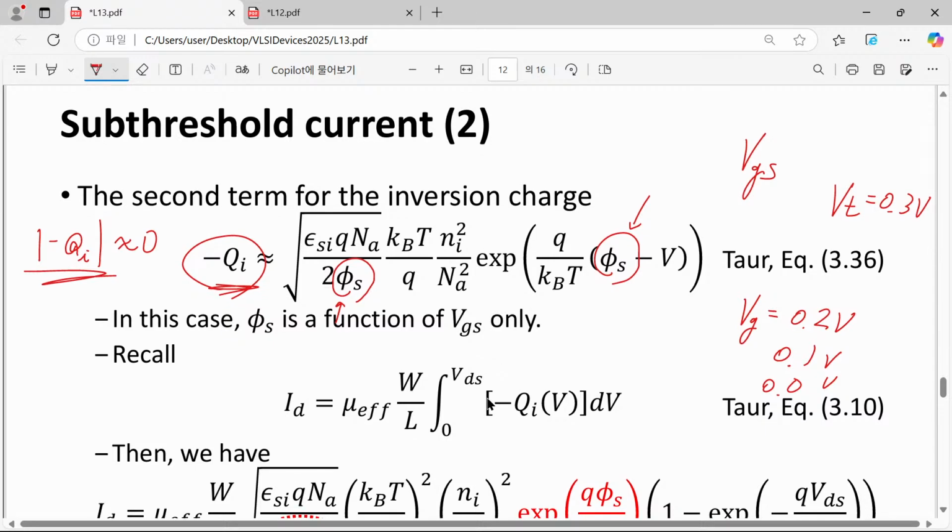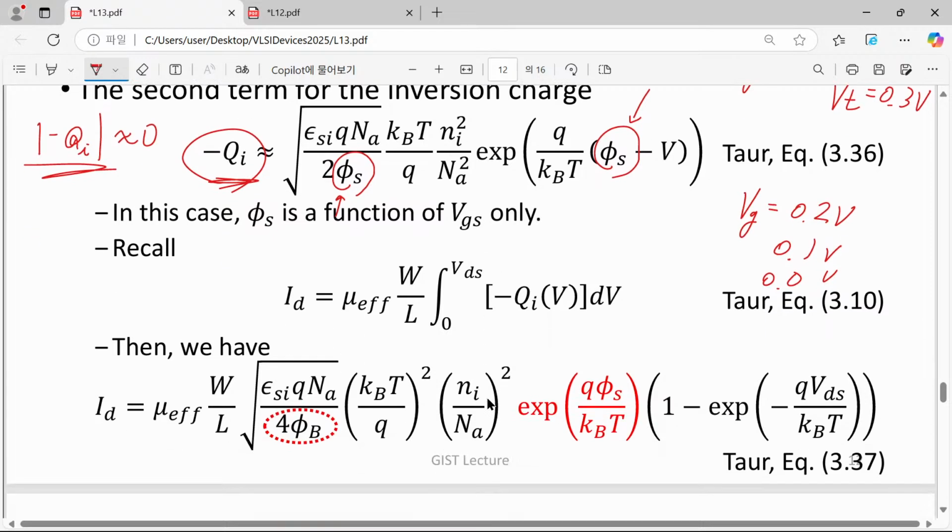As I showed here, surface potential is a function of gate potential. So if you change gate bias voltage, then surface potential will be changed accordingly. So in this case, surface potential is not pinned. Please note that the electron contribution is so small, so surface band bending is just given by the amount of depletion charge, so it really changes accordingly.